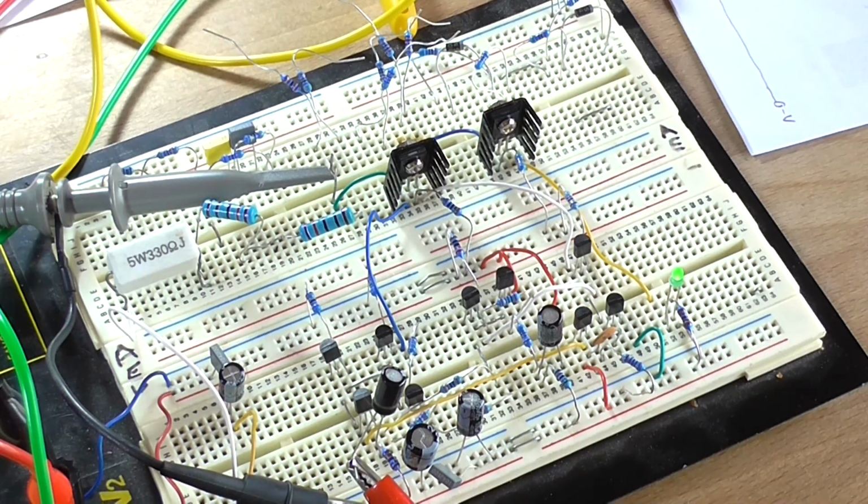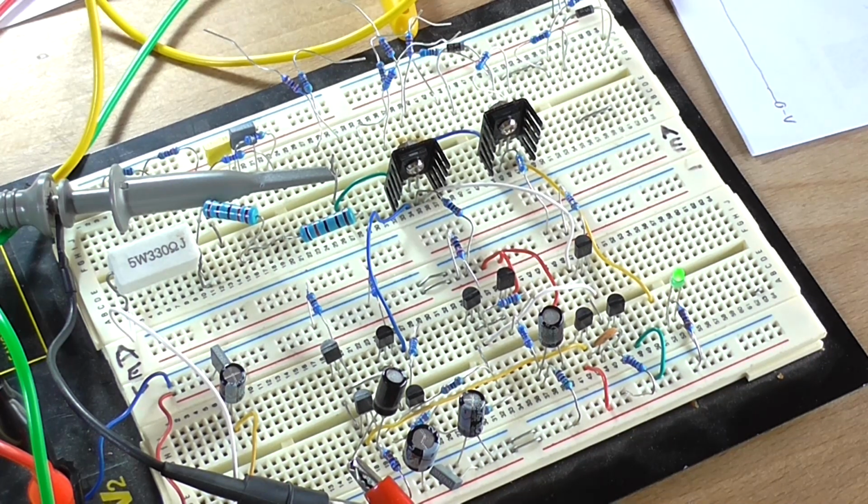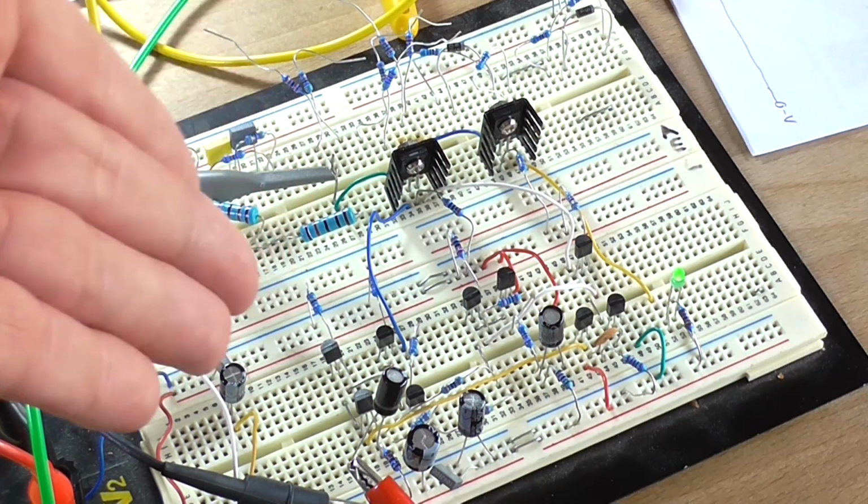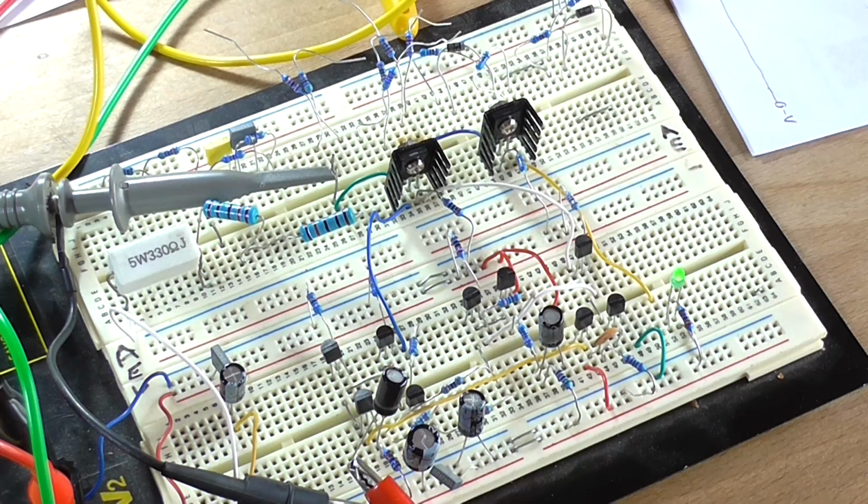Now the next burning question that people may ask, why go to all this trouble when you could just use an op-amp based solution? Why have all this discrete circuitry? Well, some people complain with headphone amplifiers using op-amps that there's just way too many transistors in the signal path, which I agree. The NE5532, for instance, has quite a fair few transistors in the signal path, mainly for its short circuit protection and all that sort of jazz. But with a discrete design, you can actually get the distortion fairly low, which is what we're aiming for.